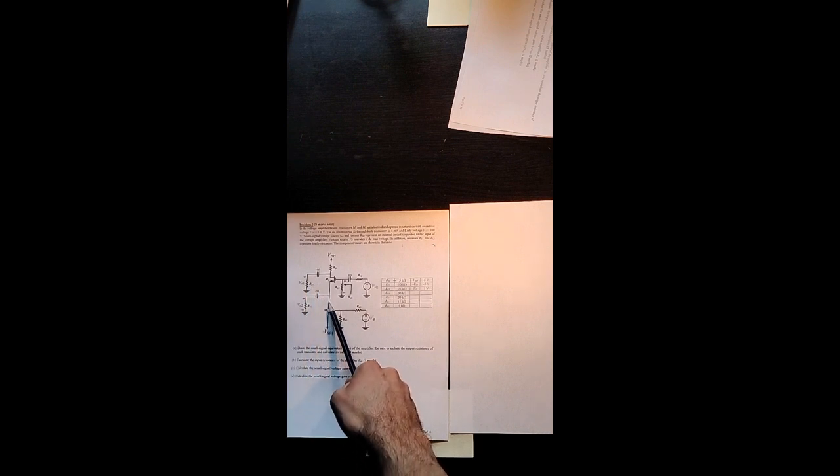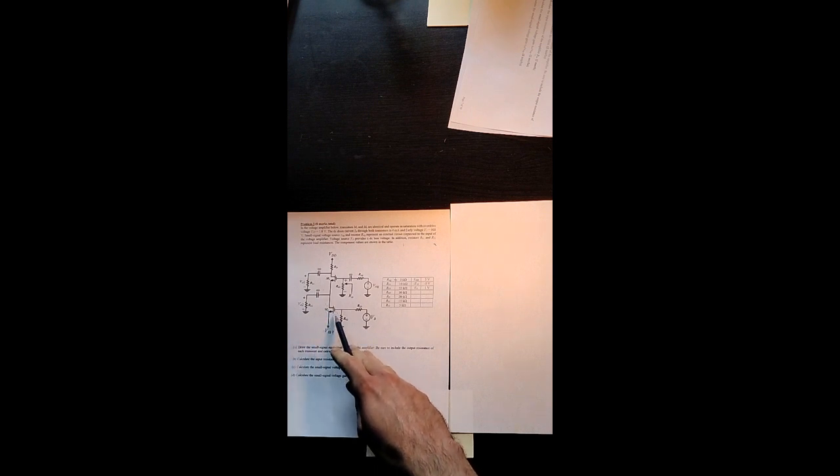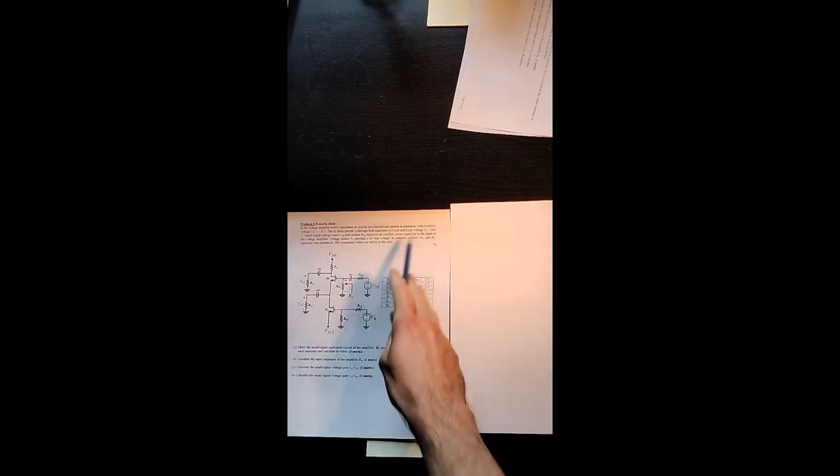I would like to make the argument that this point here doesn't matter. Of course, the voltage there matters for the amplifier, but the voltage here will not affect the amount of current going through this transistor. We've already given that is 4 milliamperes. And this whole part at the bottom doesn't change. It's just DC. So I believe that you can really just disregard the bottom half of the circuit.